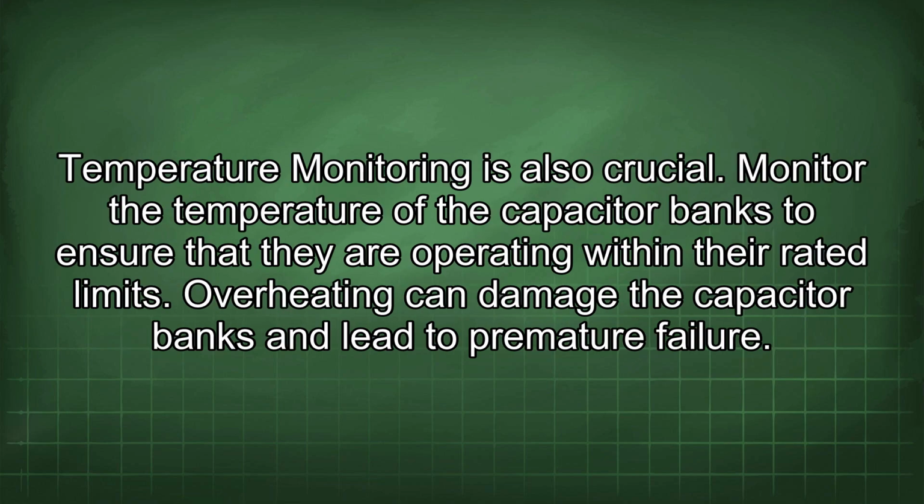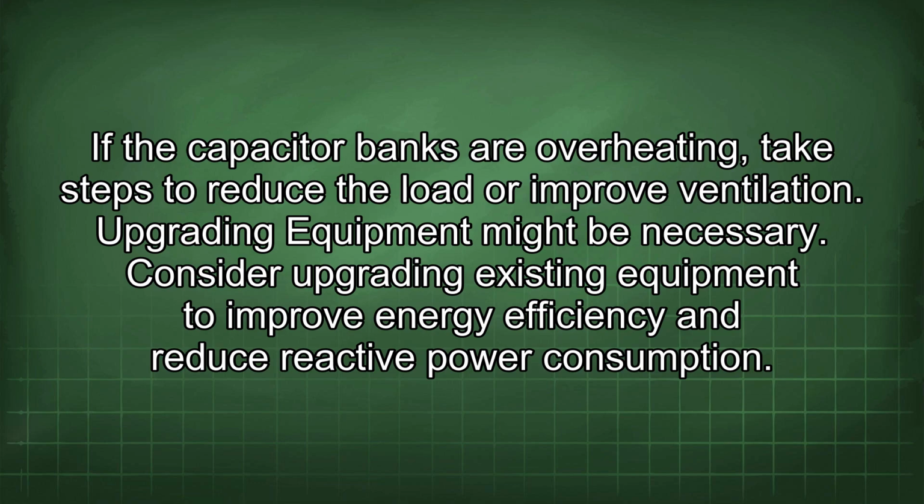Temperature monitoring is also crucial. Monitor the temperature of the capacitor banks to ensure that they are operating within their rated limits. Overheating can damage the capacitor banks and lead to premature failure. If the capacitor banks are overheating, take steps to reduce the load or improve ventilation.